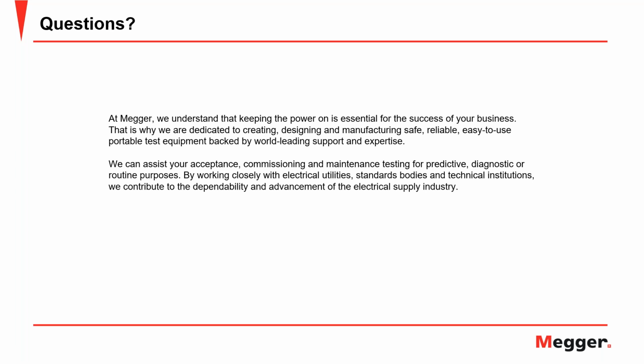So whenever we're testing the time delay for a ground fault system, it is important to perform these tests at different time delay points. So whenever we do perform that test, you want to inject 200% and perform a time delay test, and then 300% and perform a time delay test.